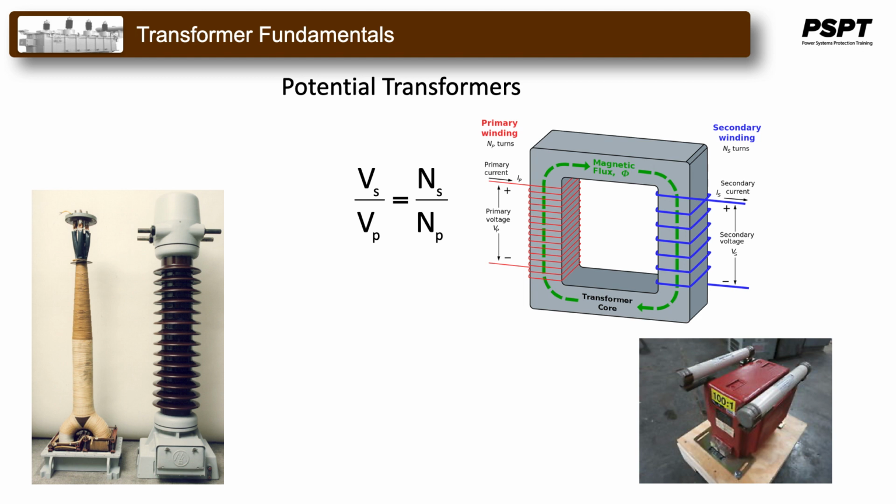The excitation current that is necessary to magnetize the iron core causes a small impedance drop and a phase shift in the primary windings. The load current that is drawn by the burden also causes another small impedance drop. Both of these produce an overall voltage drop in the transformers and introduce errors into the ratio and phase angle. The net result is that the secondary voltage is slightly different than the ratio of the turns for the transformer, and there is also a slight shift in the phase relationship.